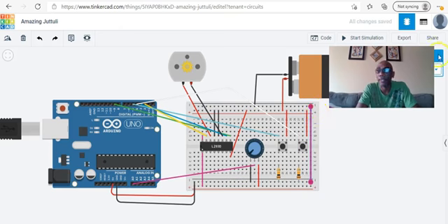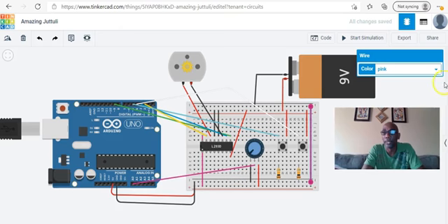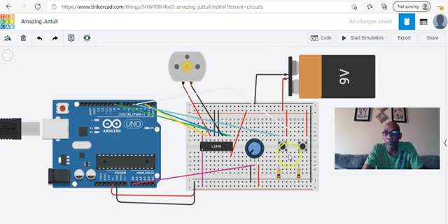And I will pull this down, and I will change this wire color to black. Okay, so this is what it should look like. My 9 volt is supplying the power to this one side. My H bridge is running 2 negatives here. It is running from this pin to the positive on this side, and from this pin to the positive from the 9 volt battery. And it is feeding power to my DC motor.